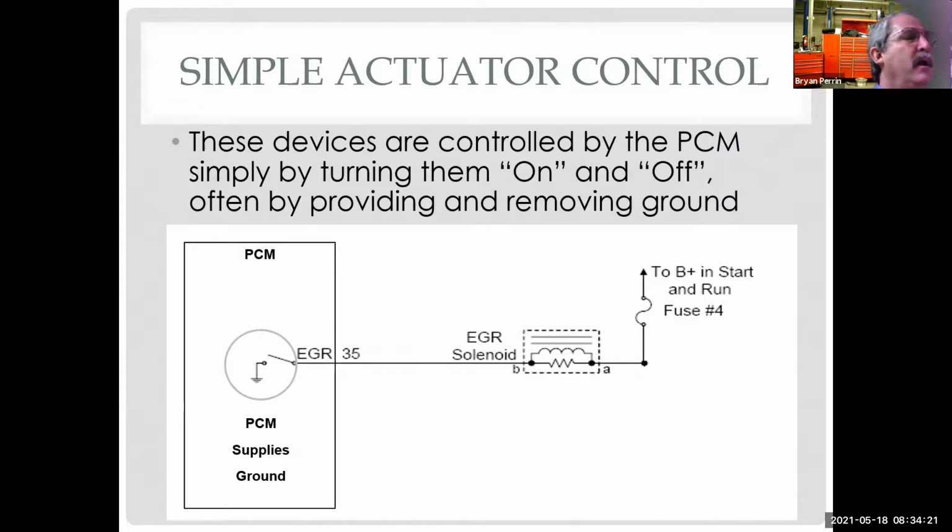So EGR might be simple. I might be able to just command it on and tell it to stay on, and then I can test it. Or most manufacturers duty cycle the EGR, but they may have a command in the scan tool where I can turn it on using the scan tool.